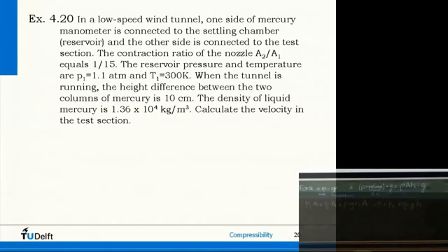So what does a manometer actually tell you? It tells you something about pressure differences, right? That's what we're typically looking for, because it's low-speed subsonic flow. Once we know pressure differences, we can transform them to velocities through Bernoulli. So this is a very handy tool, a manometer, because we know P1 minus P2 is equal to the density of our mercury or liquid times G times H.